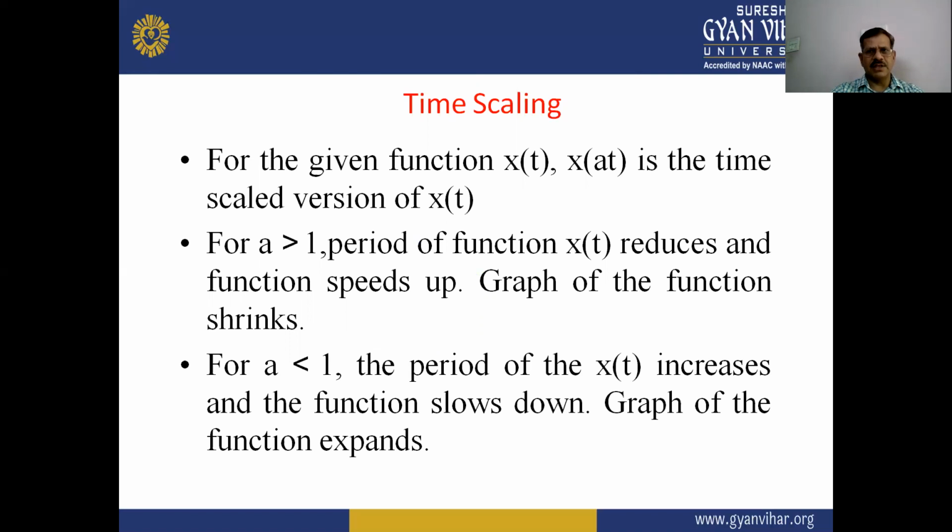Next is time scaling. In time scaling, for the given function x(t), x(at) is the time scaled version of x(t). For a greater than 1, the period of the function x(t) reduces and the function speeds up, so the graph of the function shrinks. If a is less than 1, the period of x(t) increases and the function slows down, so the graph of the function expands.